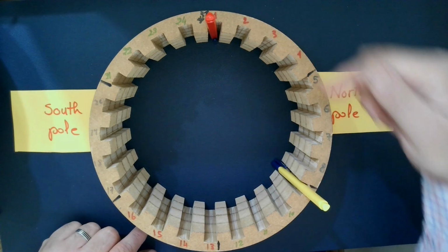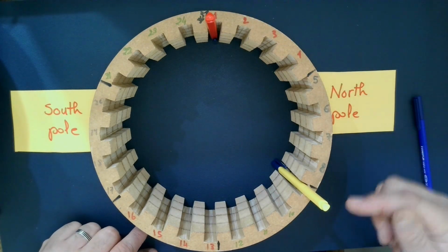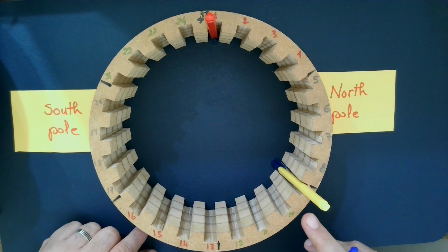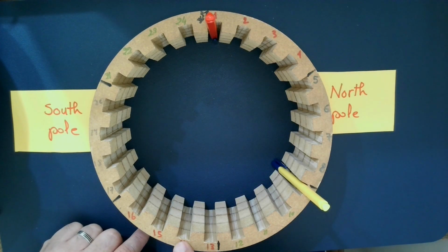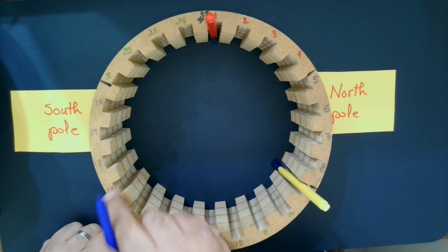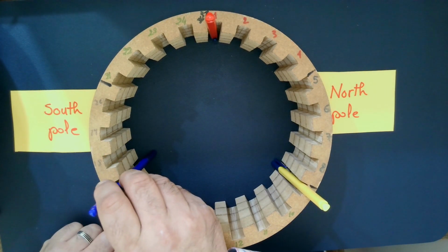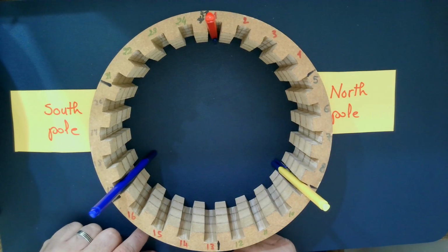So if you notice, I use a color code, red, yellow. So definitely for phase C, I'm going to use the blue. I'm going to count another 8 slots. 1, 2, 3, 4, 5, 6, 7, 8. Here will be the start of phase C. So that one will be slot number 17, the start of phase C.